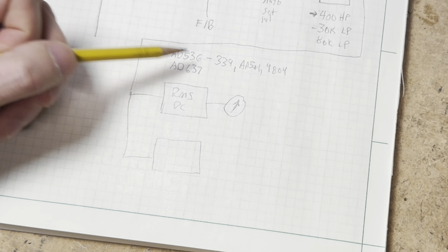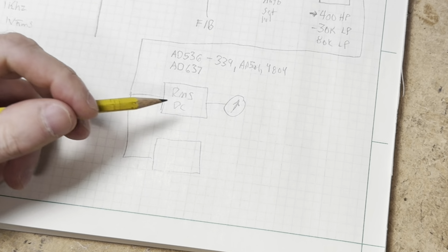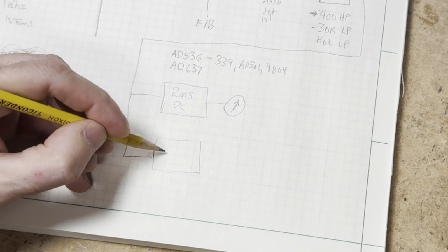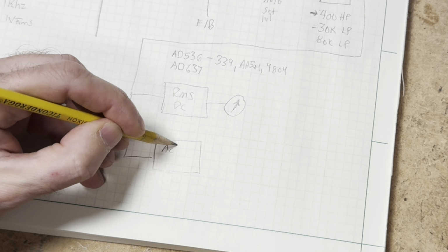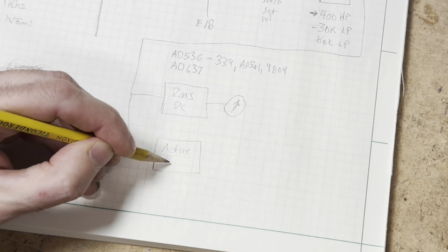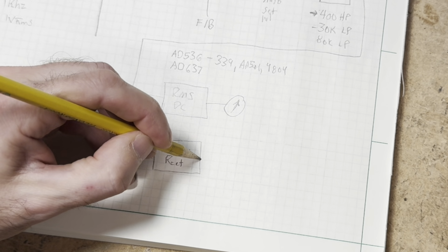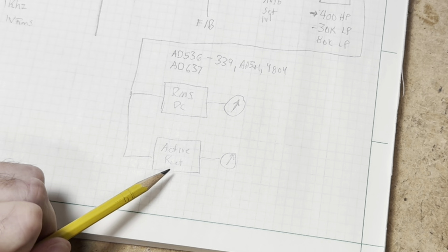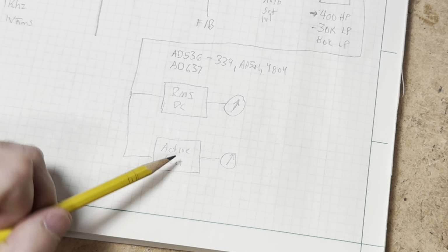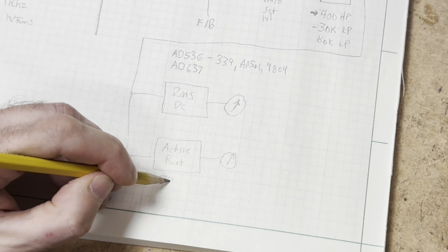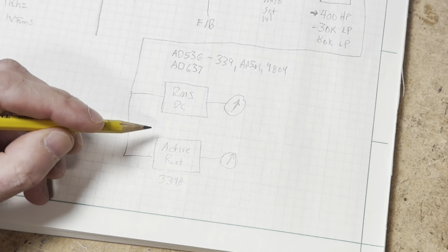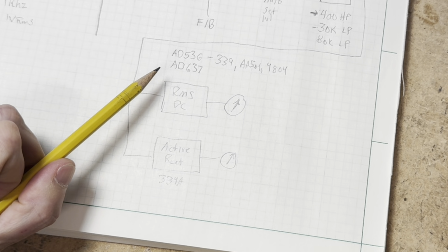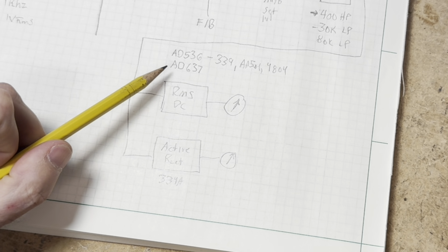Now, so we mentioned one method. The other method is to use an active rectifier that is calibrated for sine wave response. This is how some of the older instruments, like the HP 334A, work, and I believe one of the Krohn-Hite instruments uses this.